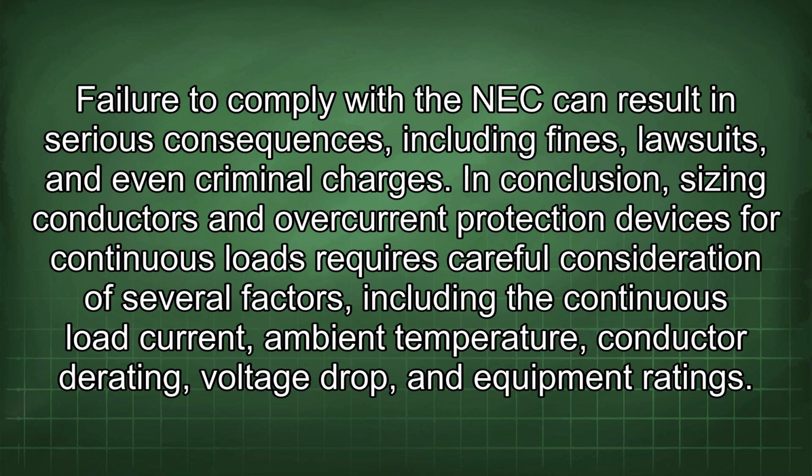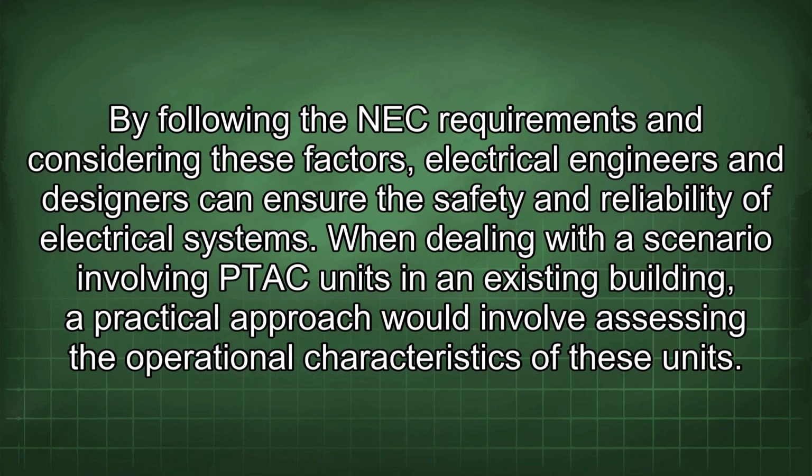In conclusion, sizing conductors and overcurrent protection devices for continuous loads requires careful consideration of several factors, including the continuous load current, ambient temperature, conductor rating, voltage drop, and equipment ratings. By following the NEC requirements and considering these factors, electrical engineers and designers can ensure the safety and reliability of electrical systems. When dealing with a scenario involving TAC units in an existing building, a practical approach would involve assessing the operational characteristics of these units.